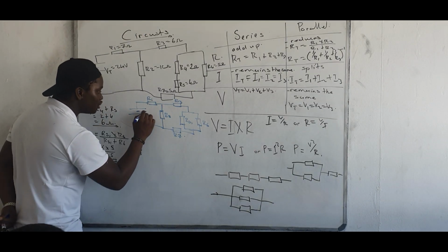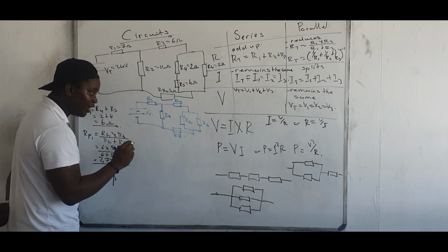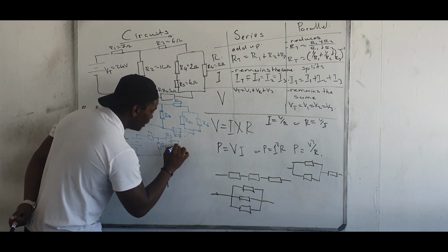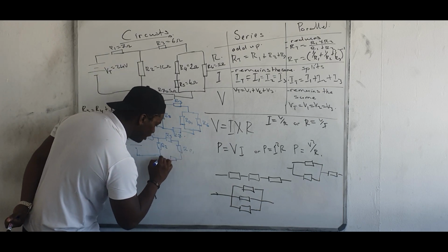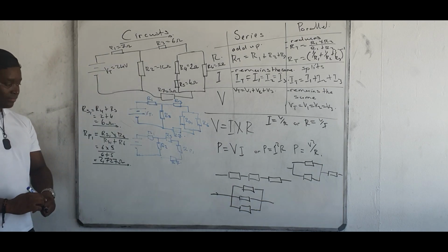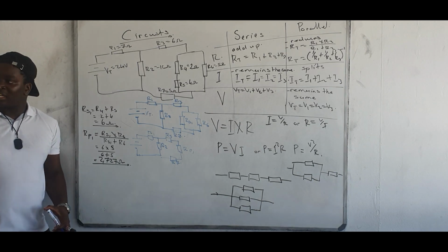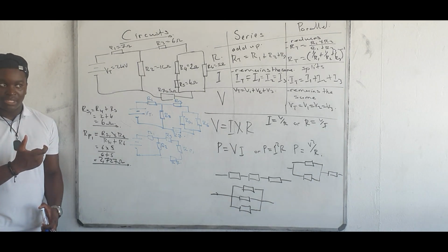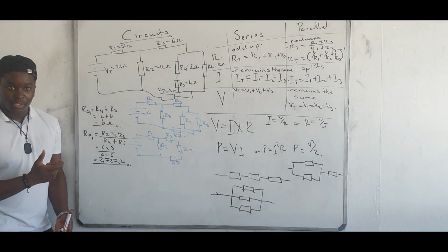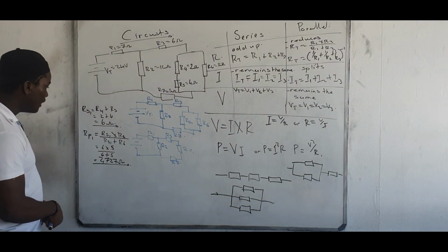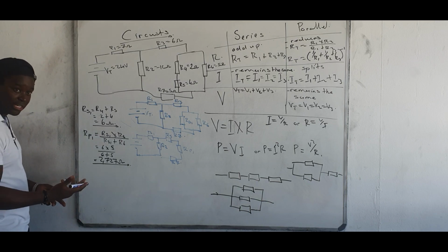So let's redraw this whole thing and see what it looks like now. Now, what's the next step? R5, RP1, and R7: are they connected in parallel or series? Series. Are you guys sure? Why? Unbroken. Are we together? So let's call it RS2, right?